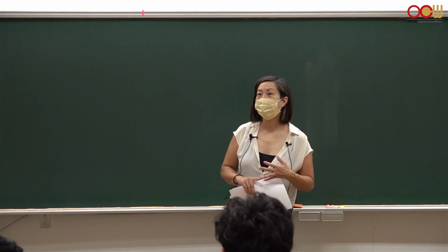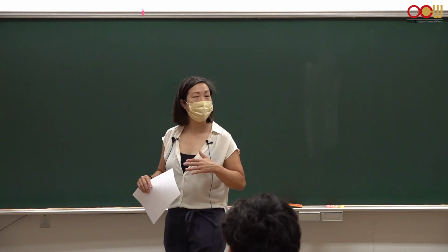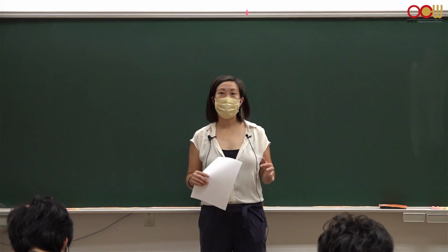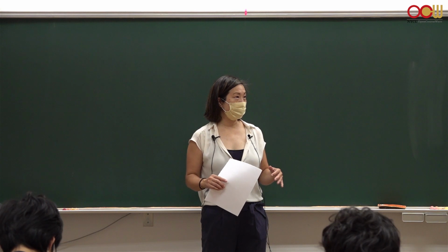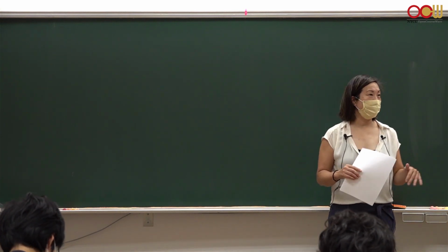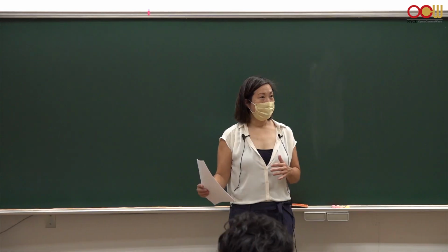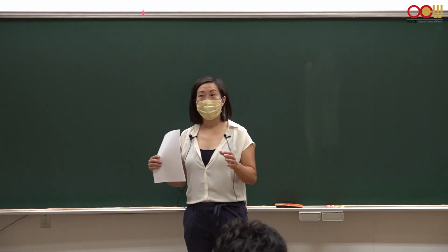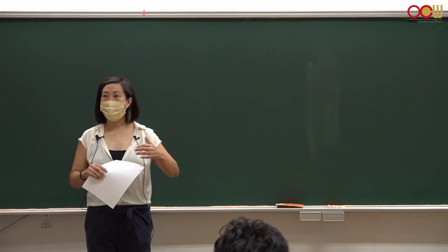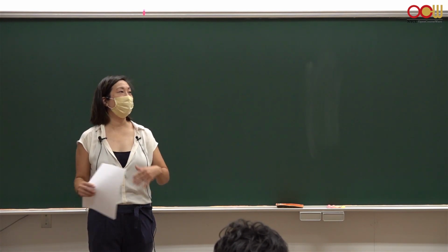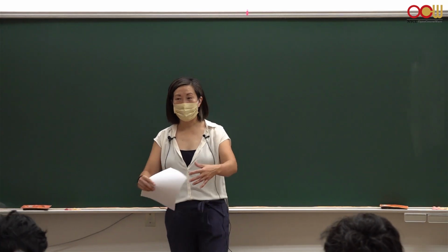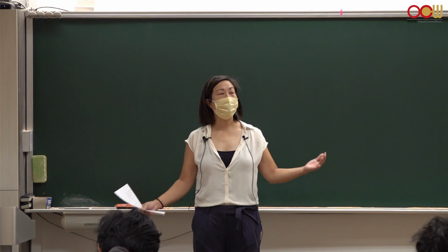So fatigue is from many, many cycles of use, and creep is when you have a constant stress, but you're using the material at elevated temperatures. And we know that materials break because of crack formation and crack propagation. So materials that can plastically deform can prevent the crack from growing very quickly. Eventually, cracks will still grow if you continue to use the material or if you continue to apply enough force